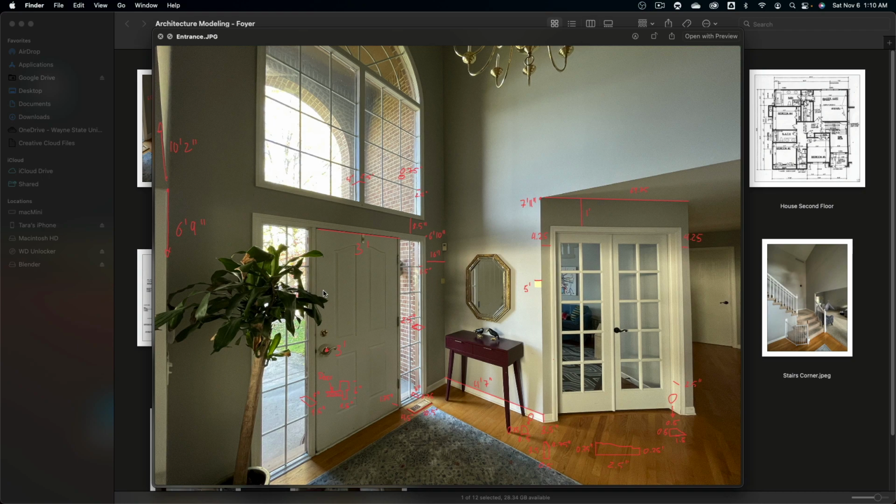Anyway, enough complaining. How do we find the opening for this area and the window? Pretty much the same way how we did it here. I did measurements from the outside, and then I took height measurements and then distance measurements. That basically then told me exactly where, for example, the trim has to start.